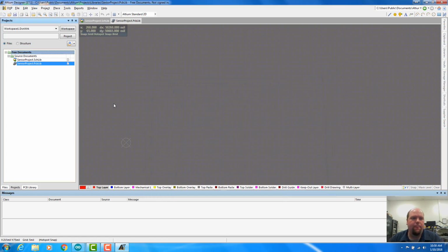Senior project. Okay. So now we've got those two files saved in a location that we know. If you are creating a library for your senior project, it's good to keep it organized somewhere. Don't have it be within the file for any particular board design, any particular PCB. Have it out somewhere in a libraries folder or in the Altium default folder. But just know where you keep it, know where you save it, make sure it's somewhere that gets backed up, make sure it's somewhere that moves with your file.